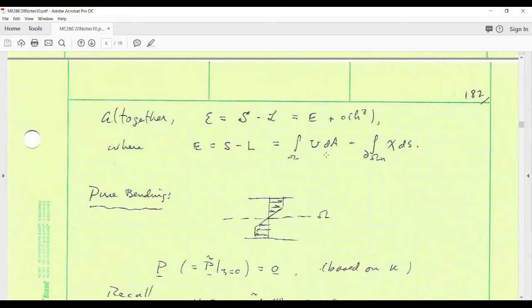So that's a bit of a complication relative to three-dimensional theory, in which you have a potential energy that just depends on one unknown vector field, the deformation, chi hat. Here we have an energy. It's much simpler because we're dealing only with a two-dimensional theory now, but it's got more structure because the energy depends through these integrands on r, the deformation of the midplane, and d, its first order through thickness derivative at the midplane, plus g plus h.